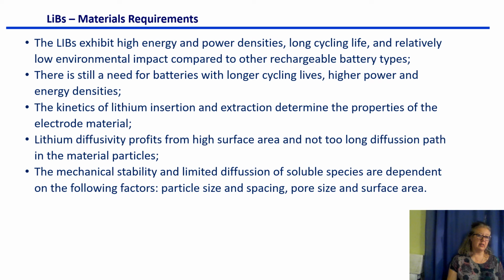Lithium diffusivity benefits from high surface area and not too long diffusion path in the material particles. The mechanical stability and limited diffusion of soluble species are heavily dependent on factors such as particle size and spacing, pore size, and surface area.